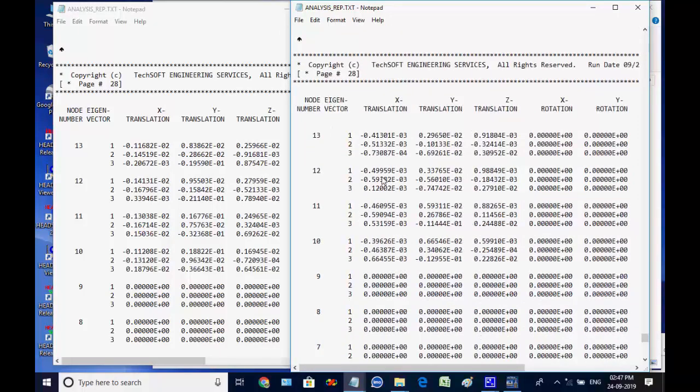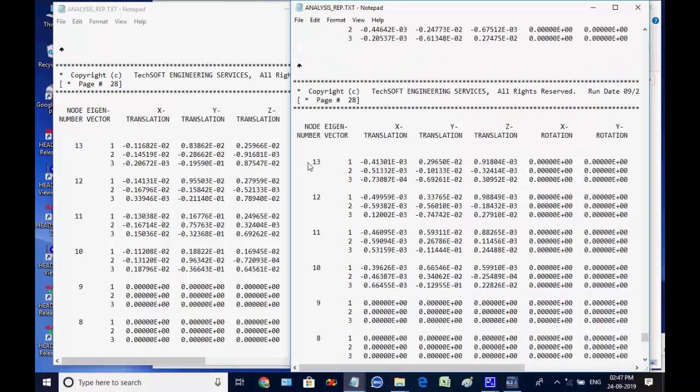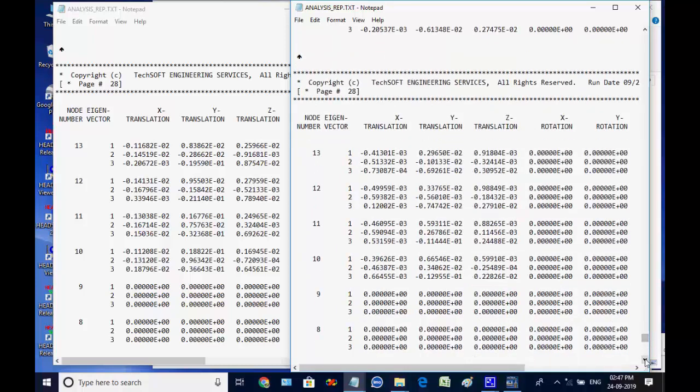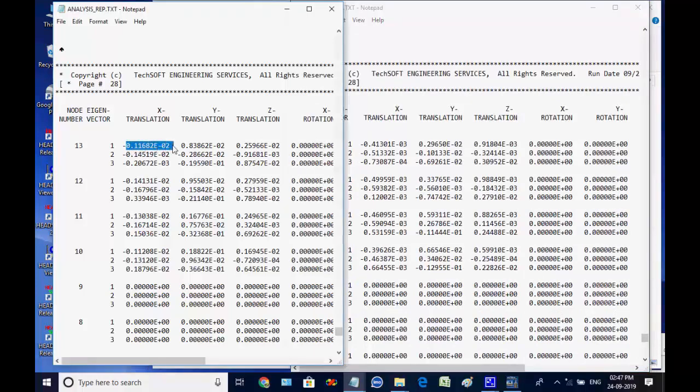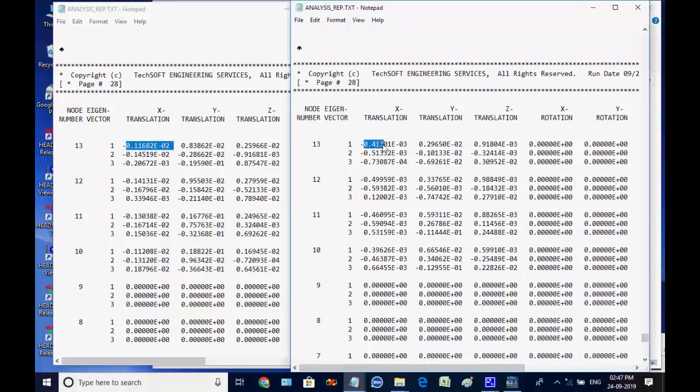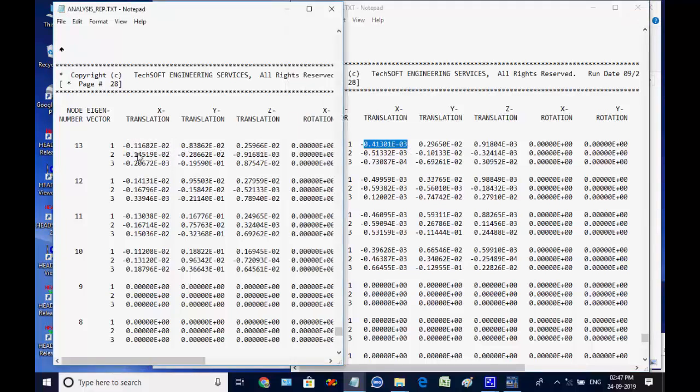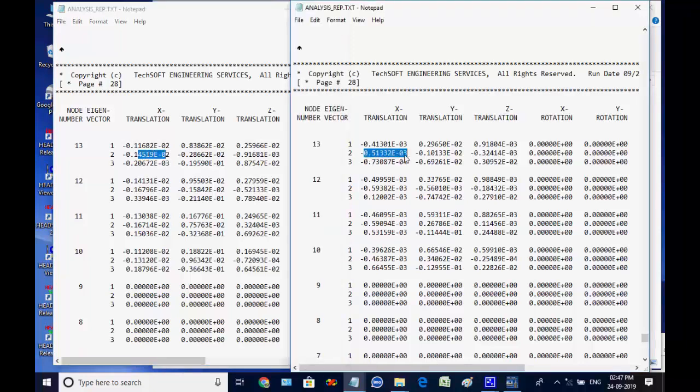We open the analysis report files from Project Folder Design Job Number 1 and from Folder Design Job Number 2, and we can compare the effects of resizing of the structure on the analysis results. Other similar trials can be done by various resizing of the model, to decide the final size of the block structure for the machine foundation by controlling the effect of vibration by reducing the translational displacements by the same applied dynamic forces.